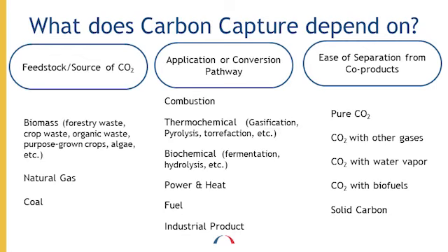And then whether we apply them for production of fuel or heat, that also determines what kind of carbon capture technology we can apply and the concentration of CO2 we can get. As CO2 is generated, the ease of separation from other co-products: is it pure CO2 that's coming off the stream? Is it produced with water vapor or other liquid products? Or is it solid carbon, which naturally has physical separation capabilities?